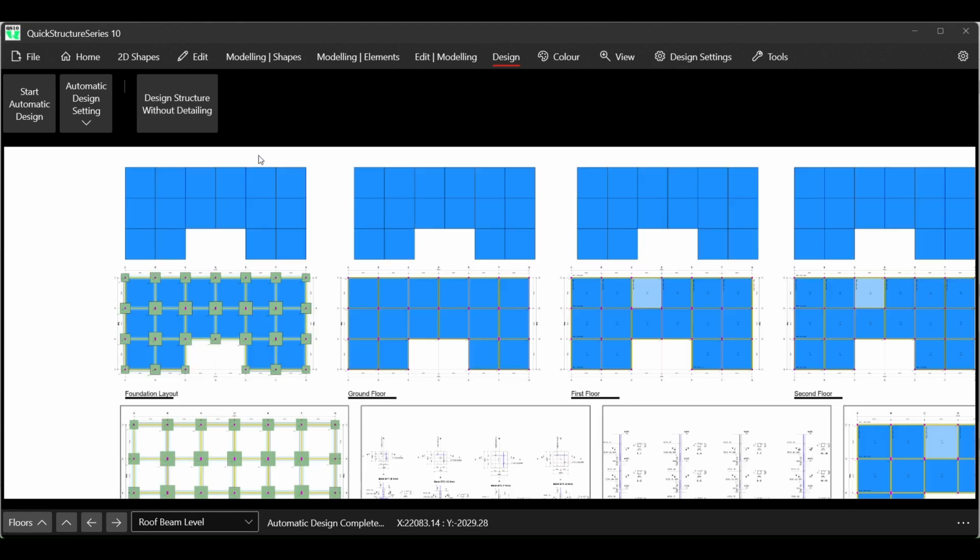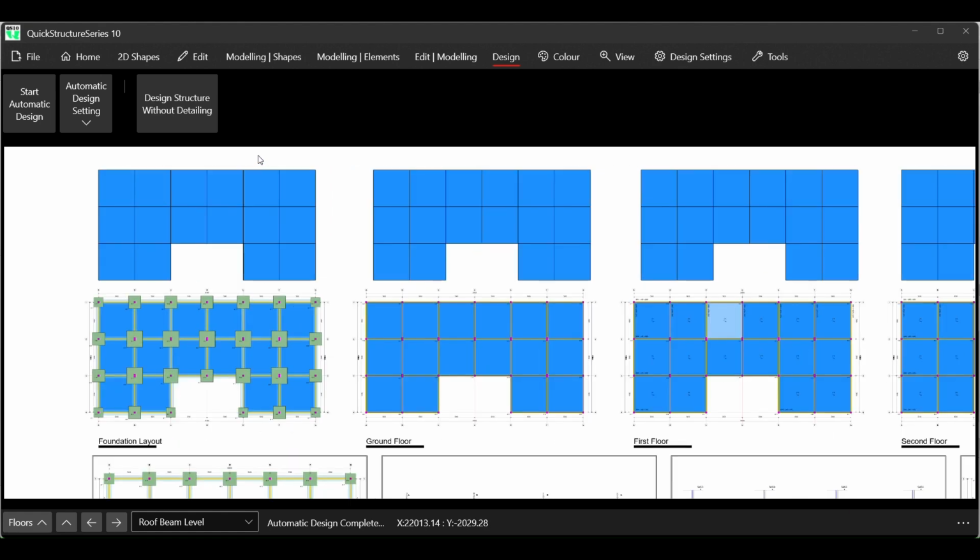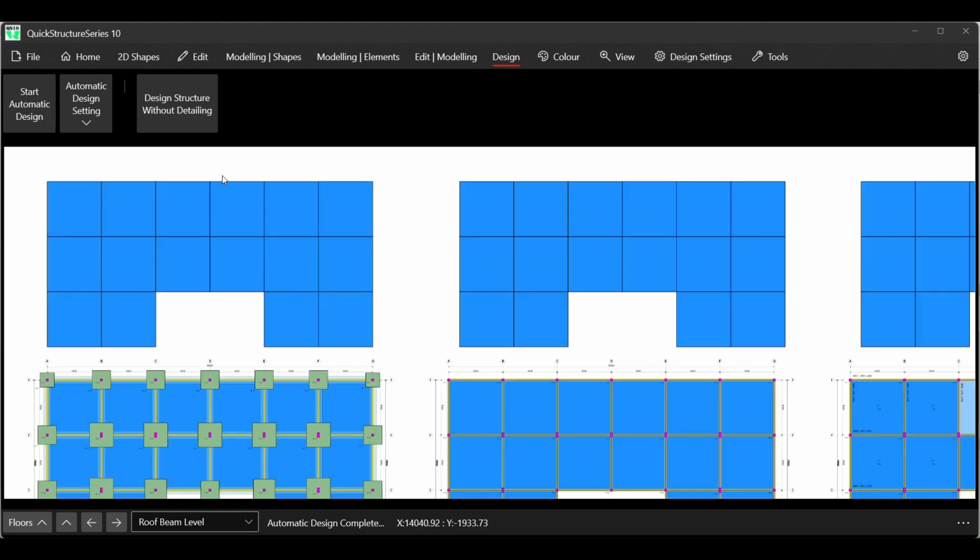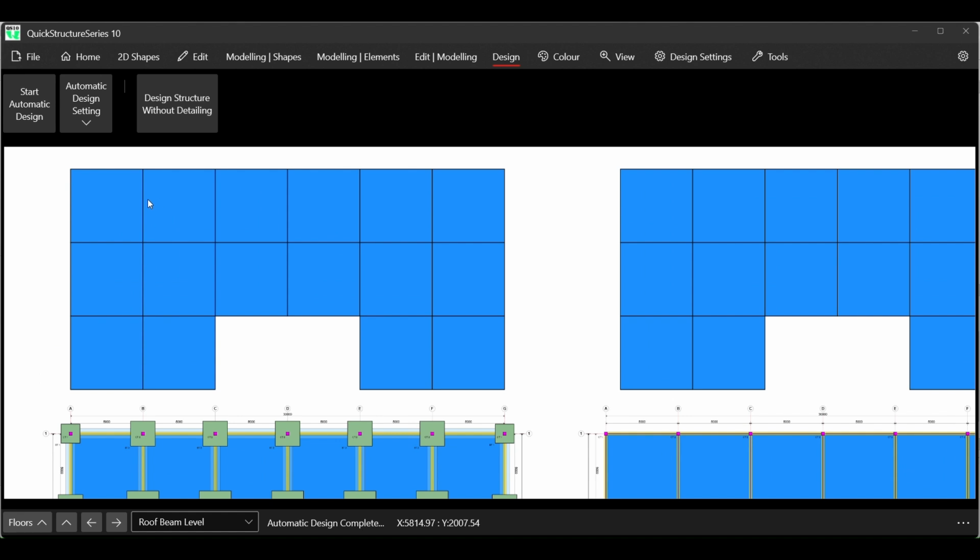And this again is probably the method we advise, whereby you actually bring in the shapes, the rectangular shapes, first into the software, and then you add it as a floor. Okay, and again, as I said, once you have brought this into this level where you have the rectangles, then the job is done. It's just as what we have learned all the while, which is modeling with shapes, because at this point you have your rectangular shapes, and then the next thing is to add them as floors.